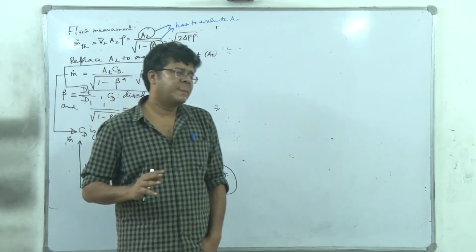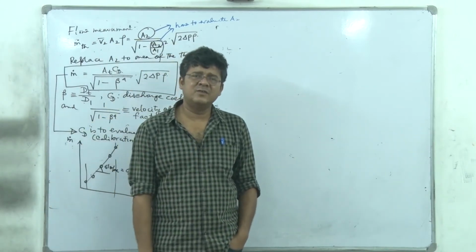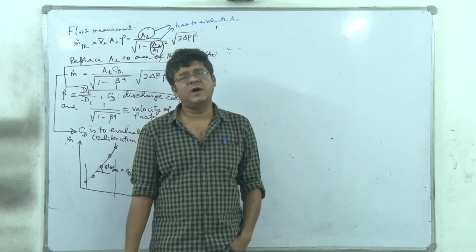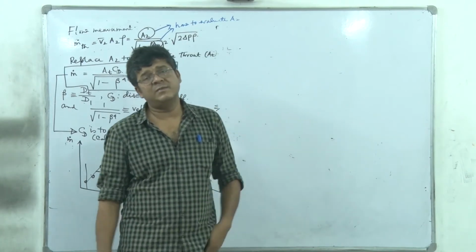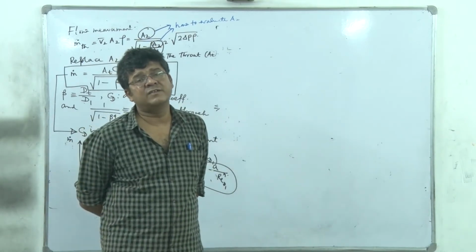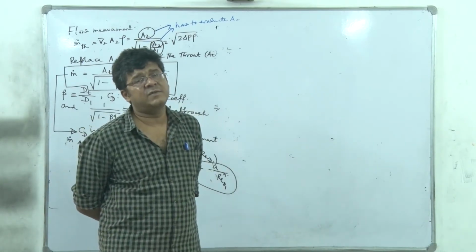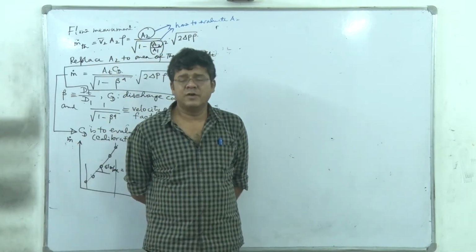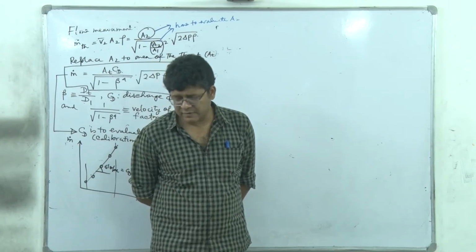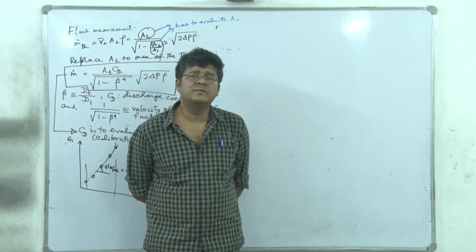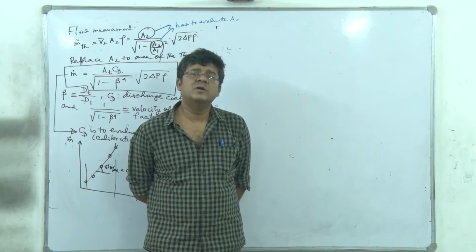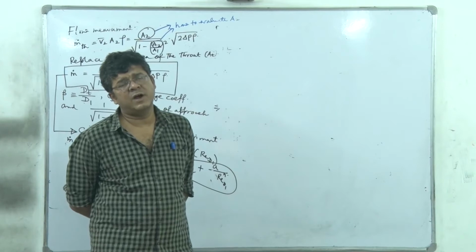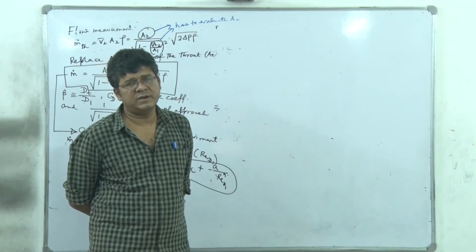But commonly, if the pipe size is large, then no matter whatever is the capital cost, we must go for Venturi meter. But for small pipe size, we definitely do not, because in large pipe size the pressure itself is costly, right? As we have to use a large size pump and there will be huge power investment. So for large pipe size, we have to pay specific attention to permanent pressure drop, and that's why Venturi meters are recommended, whereas for small to moderate pipe size, Orifice meters are recommended.